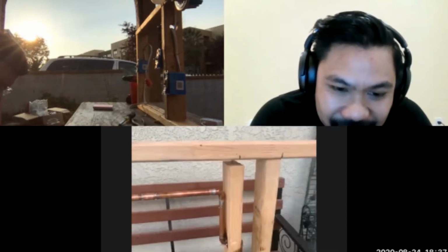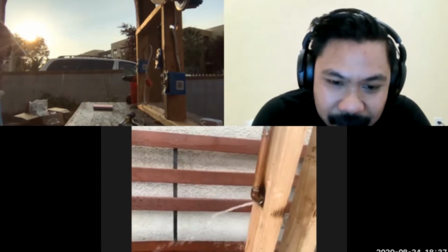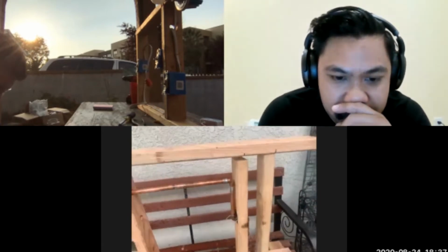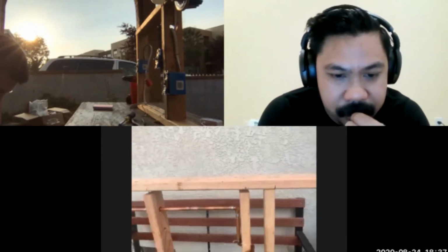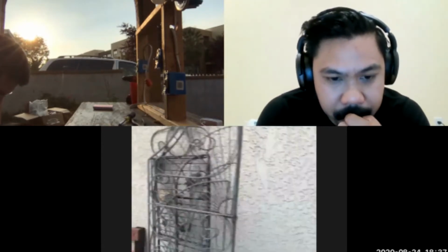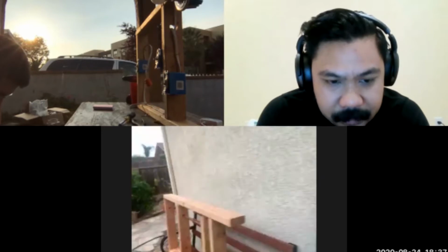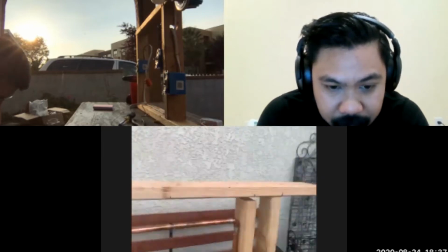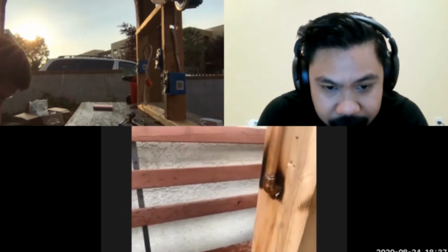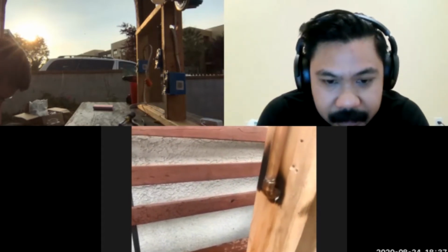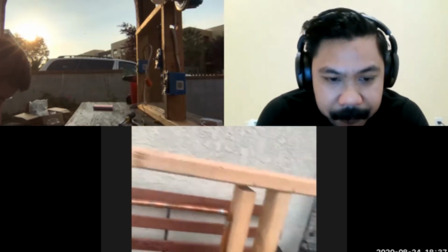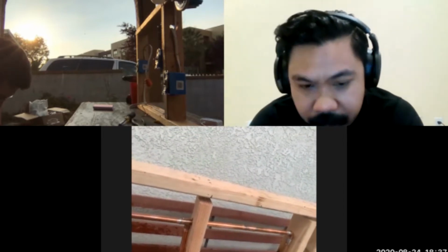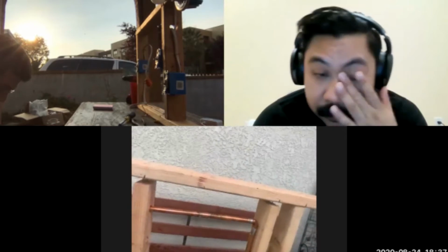It's actually coming out worse than it did last time. Yeah, and I think there might have been a little bit of moisture still in there. That's my guess, because I can see the solder. The solder itself kind of solidified on the outside. So you might have heated enough, but the problem is, you know what? I think the best thing for you to do right now is to take out the joint that's in the middle and put a new one.